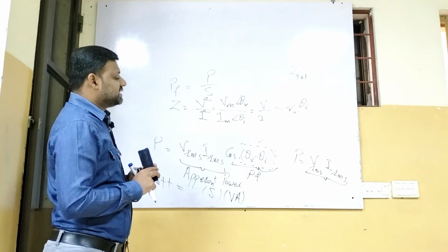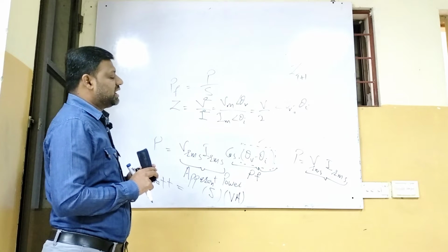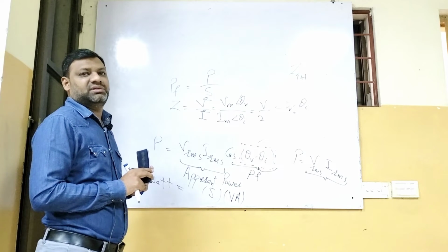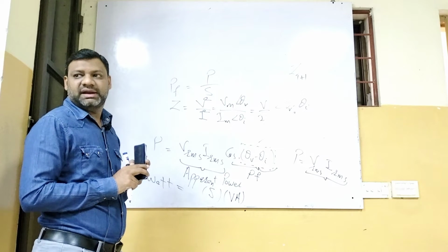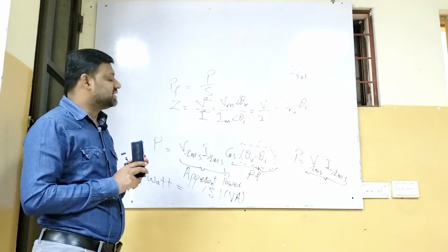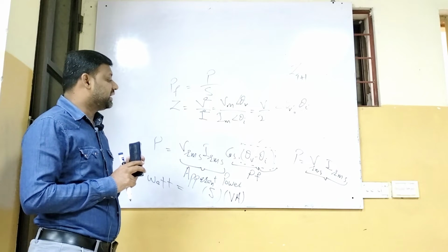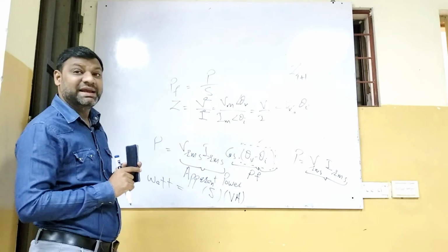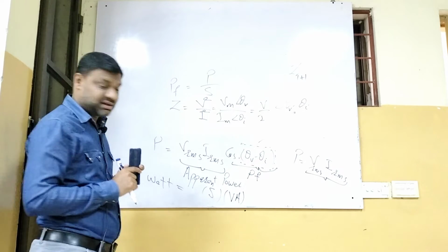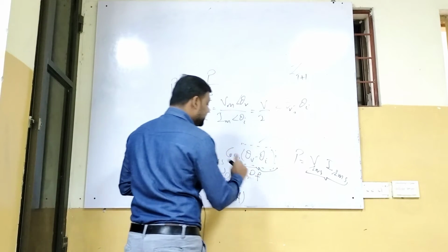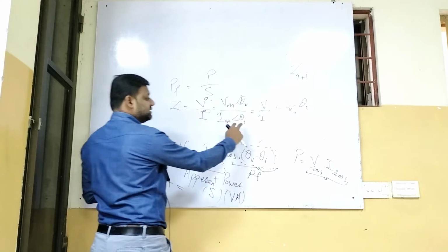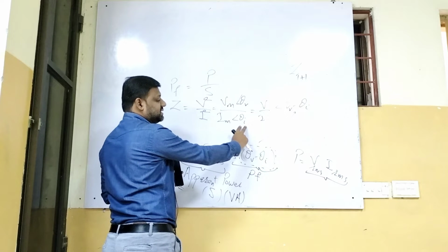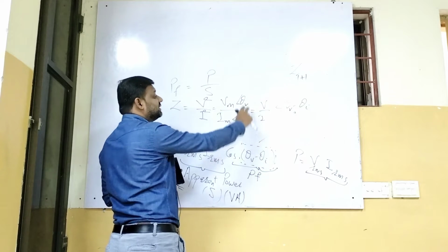One more step. Power factor also provides us the information about whether the reactance part is capacitive or inductive. The power is leading or lagging. If current is leading, it has a greater phase angle than voltage.